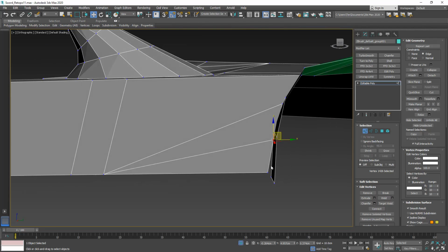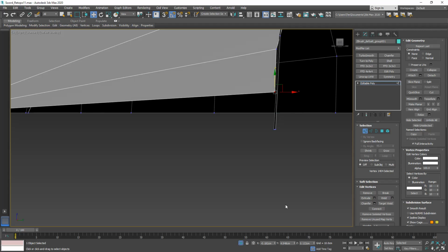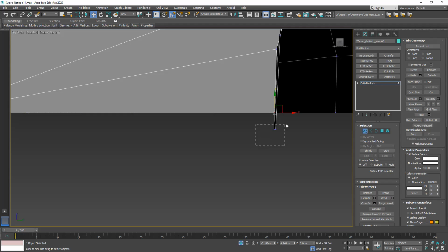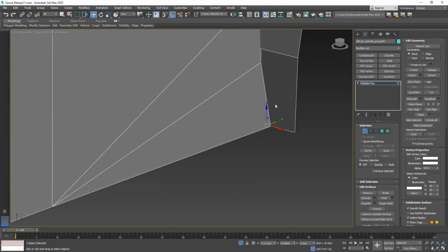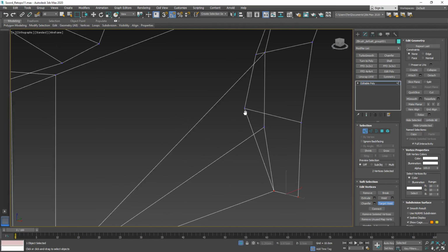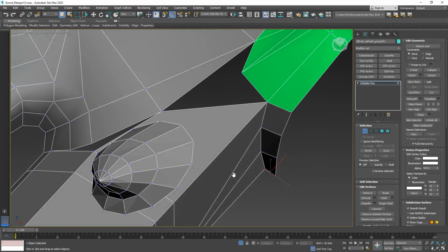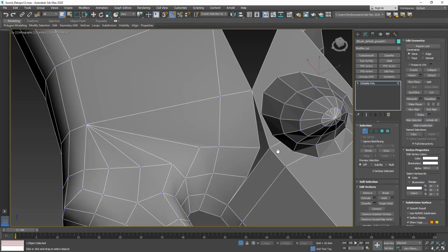And this one here, I'm gonna go out of the edge constraint mode, go over here to our right orthographic view, and make sure that this vertex point here on the Z axis is at 0. These two here, I'm gonna also put them to 0 by right-clicking this little arrow with the right mouse button. And now we can go over here to target weld and then connect these vertex points with the ones that we were just creating there with the cut tool. And that way we already have this here combined.